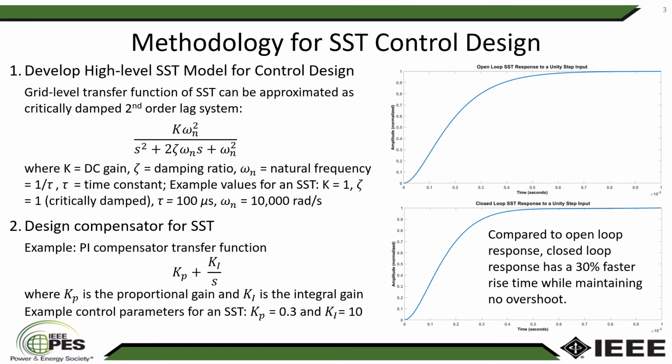The first step is to design a very high-level model for the SST. In this case, since we're only looking at grid-level behavior, it can be approximated very well by a critically damped second-order lag system, as you see there.